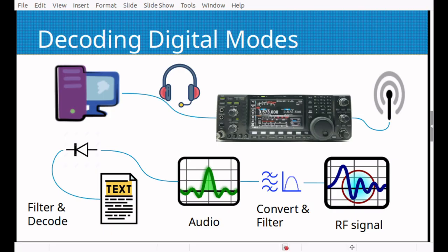This is the rig I have. It's an ICOM 7600, and I'm going to explain very simply at a high level how the signal-to-noise ratio affects decoding, and then I'll get into much more detail later on. The ICOM 7600 receives the signal off an antenna. All the digital modes, as far as I know, are always modulated in upper sideband. The ICOM 7600 has a particular upper sideband setting called D1 through D3, which allows you to customize how you're going to actually receive that digital signal.